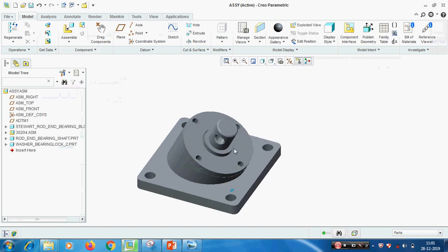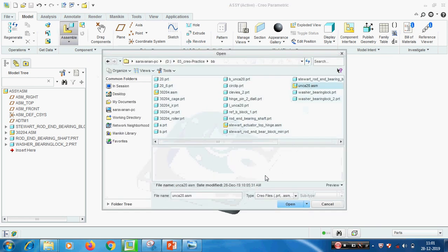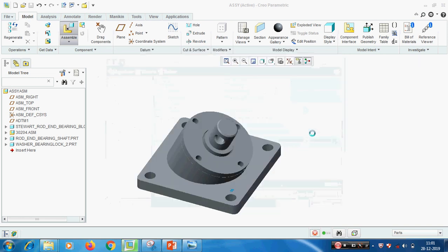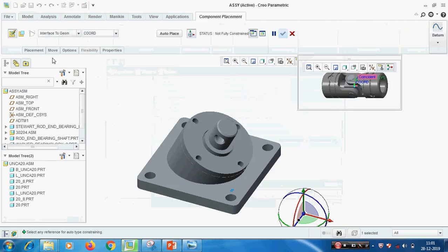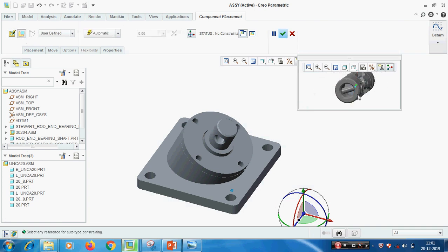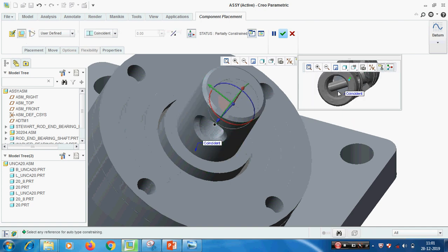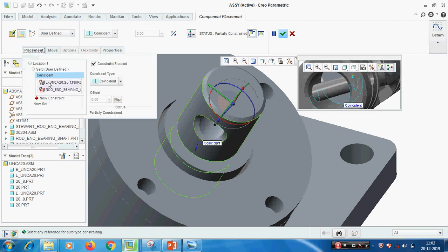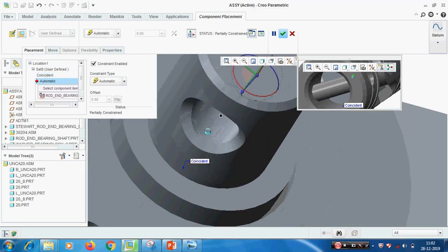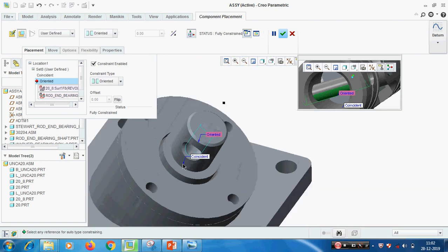Then we have to connect the universal joint. This is a Misumi component, universal joint. Then coincident, this should be inserted into this. Then this is a pin, it should not be in this part. This is a bought out item, so it is available in the catalog like this. So we have to coincide this surface, then insert a pin, one pin with this and this one. Okay.